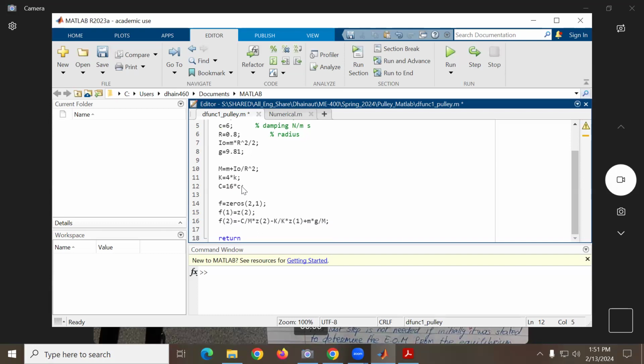Yeah, from the equation of motion. If you want, we can put mg or not. So basically, we have all these values, and here you see that I'm putting the mg over here, no? So you see that if you do the numerical solution, you don't need to do the change of variable, no? You can just keep it over here. So we have minus C over M, minus K over M.